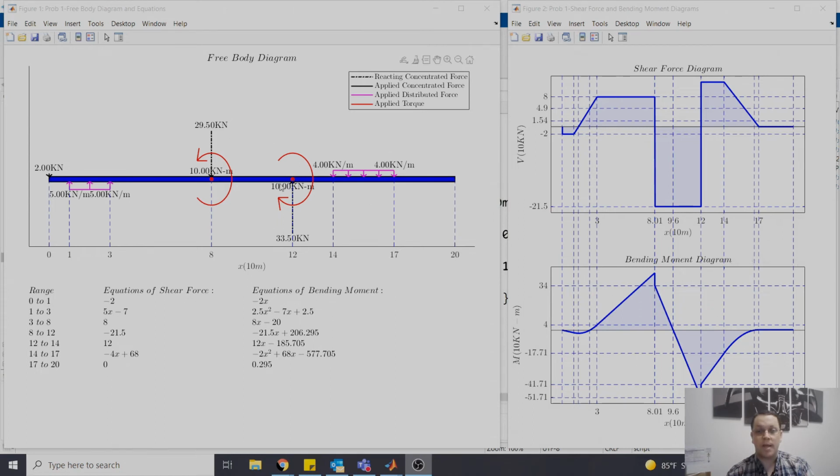And because you're supporting at the points of the bending moments, that's part of why you have the peak values at those two places. So you're going to change to a couple different sets. You want to try and do about 3 changes or 3 different sets of lengths. You don't want to use the same ones that I'm using. You just want to make sure that you're looking at 3 different sets of positions and see, okay, maybe if I support it at 20 and then at 18, what happens then? How strong do they have to be? All of those sorts of things. And you want to talk about what's different about the graph and why.